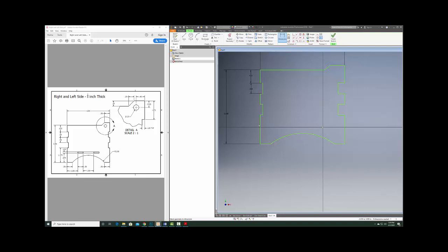Let's see here. This dimension right here probably should be figured out already, but we can just check. 0.1375. See how it already knows? Inventor has done the math and figured it out. It's going to tell me, hey, dummy, I can figure that out. I know. And you can use that just to check sometimes if you don't trust. Is that 0.5? Oh, yeah, it was 0.5. It puts it in parentheses, meaning you can't change it. It's constrained to something else, but you can keep them, you can delete them, doesn't really matter.